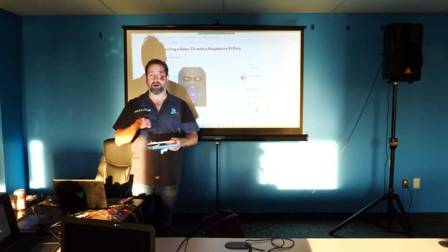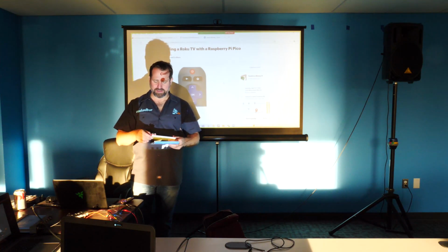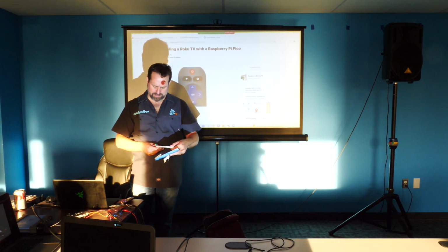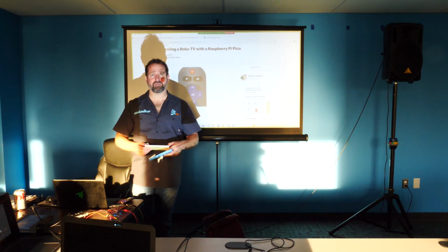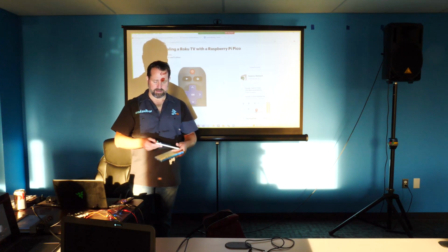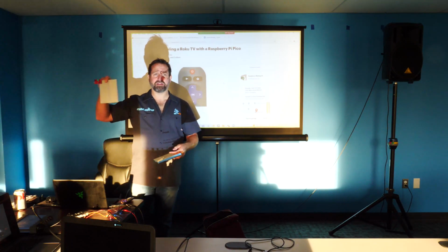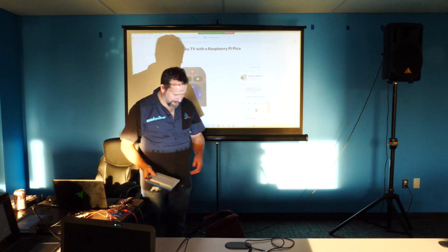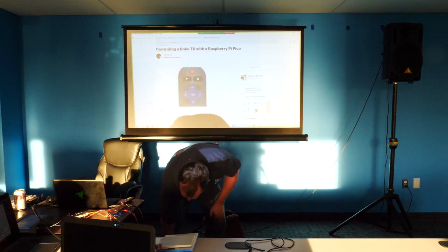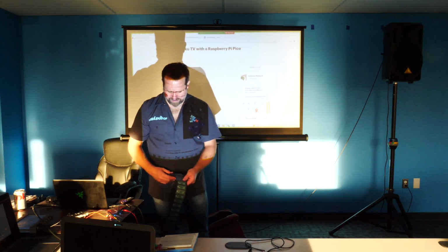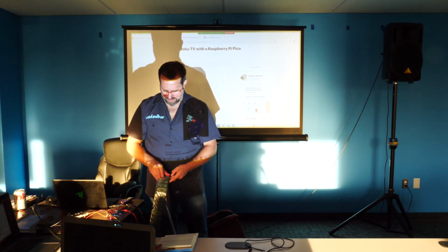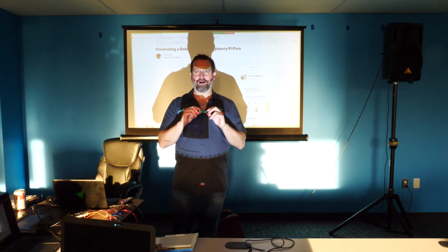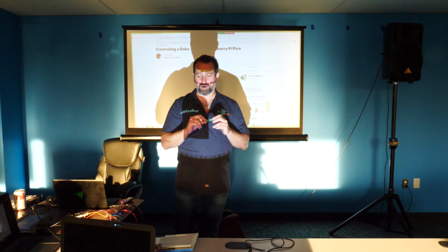And then you're going to wire up the right pins. Now there's not that many pins you have to wire up, so there's only I think 3. Or there's 3 and then 2 power pins. And that should be all you need to do in terms of building your hardware. Now, the Pi you got last week does not have headers. It's just a board with holes in it. So you need to solder headers into the board to make it work with the breadboard.